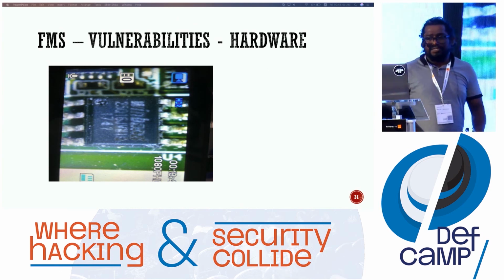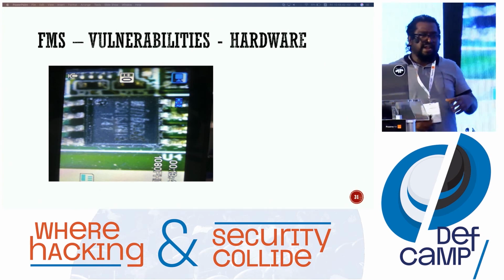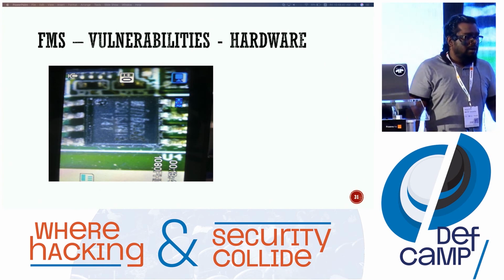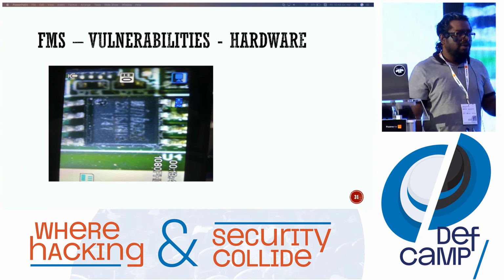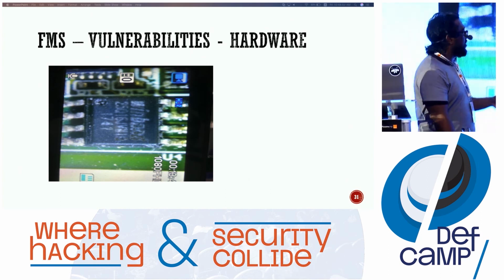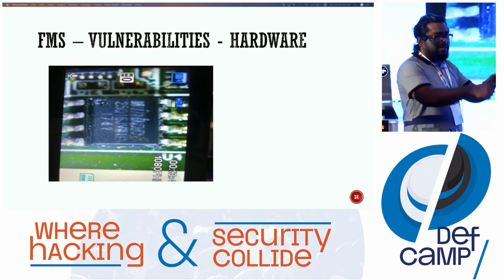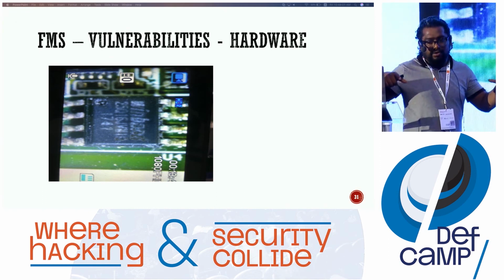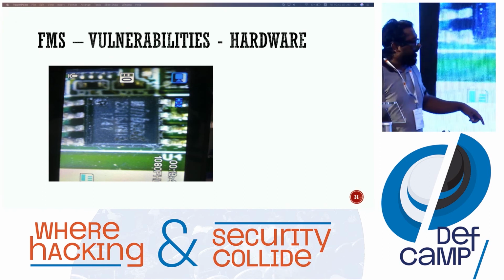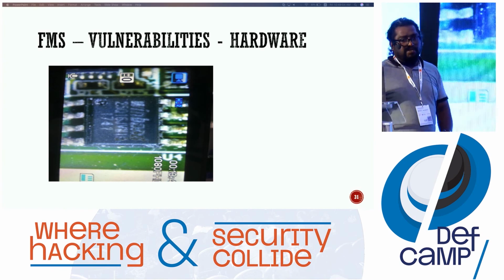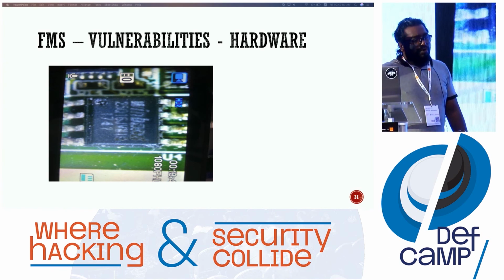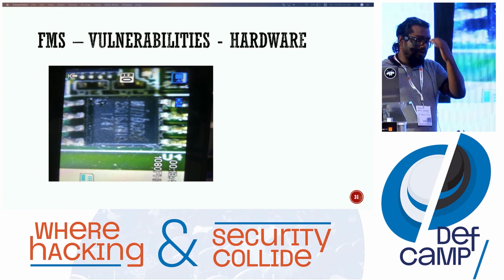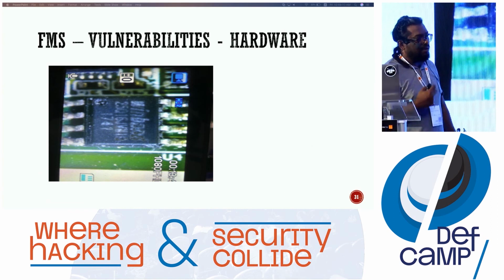Fleet management systems like an OBD2 dongle or any kind of TCU, transmission control unit or telematic control unit, reside in the car network, and from there they connect with the GPS, and from the GPS through GSM to the cloud, and the cloud to your PC or mobile.